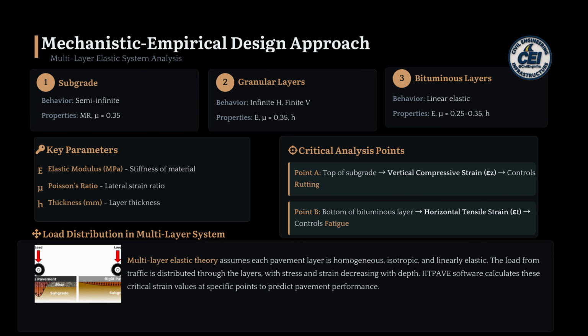Now let's move to the science behind it. On which theory is IRC 37-2018 based? It is based on the multilayer elastic theory. Friends, we consider the entire pavement as a multilayer elastic system. At the bottom is the subgrade, which is assumed to be semi-infinite, meaning it extends infinitely in the downward direction but has a defined surface at the top.